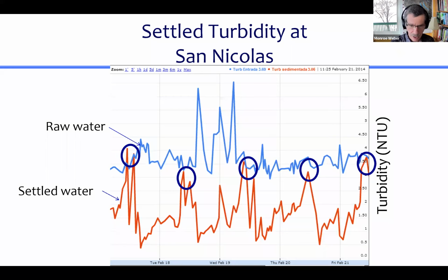And so I don't have that data, but indeed the temperature was going up nicely every day, significantly. And that meant that the water at noon, the water coming into the plant is warmer than the water that is in the plant. So you have a tank of water, like in the sedimentation tank, and it's kind of cool, and you have warm water coming in the bottom.